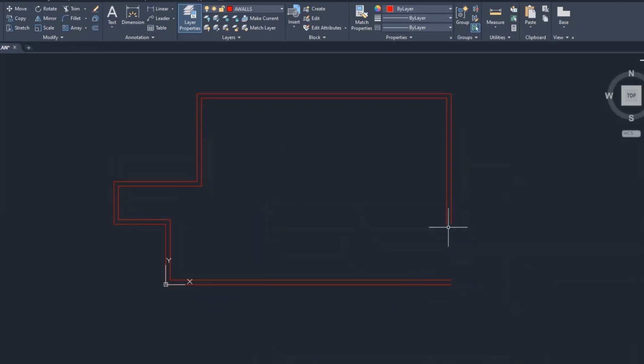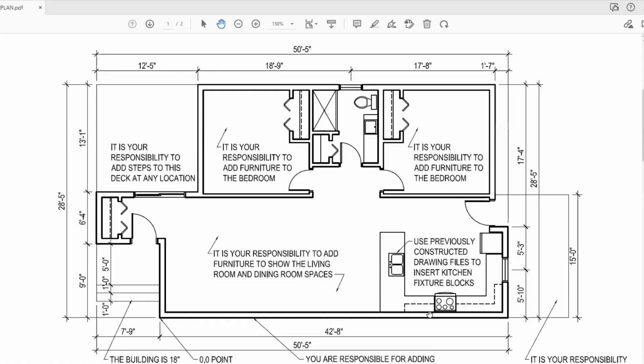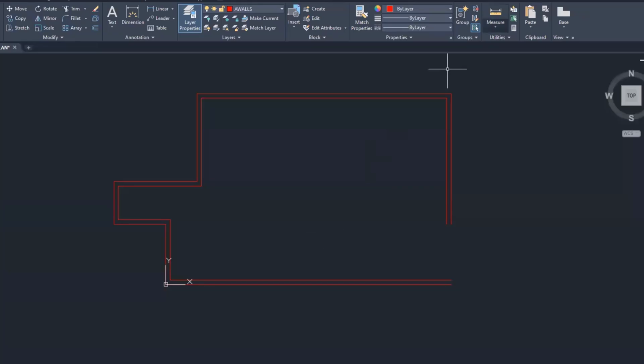And now I'm really trying to figure out what's going on with my dimensions. So I need to do some double checking here. If I start it, that is 42'8" out here, and then it's 7'9" in that direction. So I need to double check and make sure that this is 7'9" and that's 42'8". And I prefer to go the old fashioned way, which is distance from here to there, 42'8". Great, tap the escape key. My keyboard shortcut is DI, enter. And I go from here to there, and it is 7'9". Very interesting, because it should be offset a little bit there.